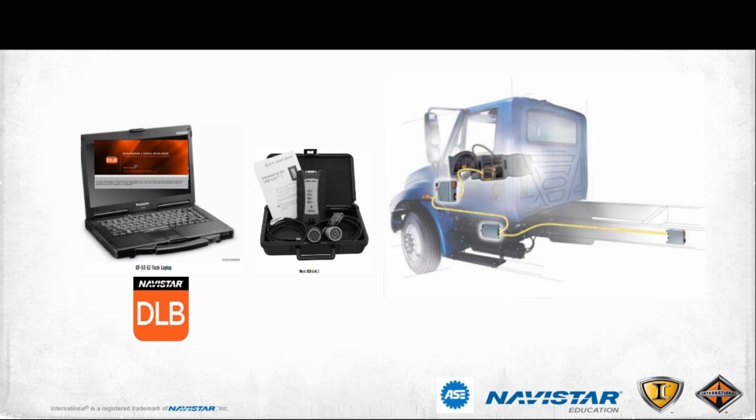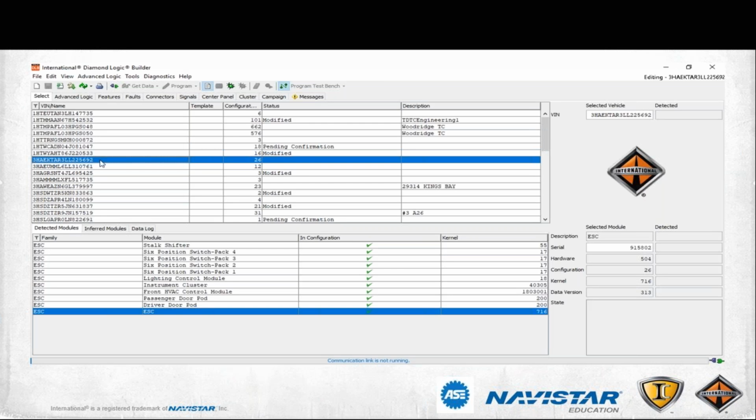Very simply, we can go into diagnostics. This software will report faults out of non-Navistar modules. So if it's a Cummins engine, if it's a Bendix brake system, Wabco brakes, Eaton, Allison transmissions, this software will report faults basically out of anything that's reporting on the J1939 powertrain data link. And it will also clear faults, even out of those third-party modules.